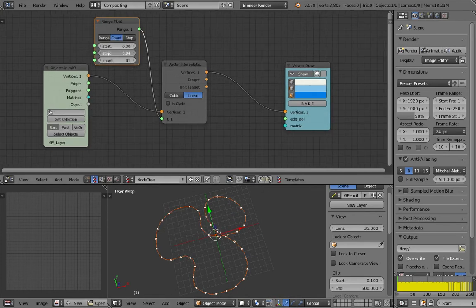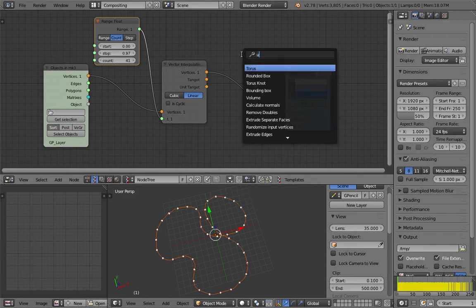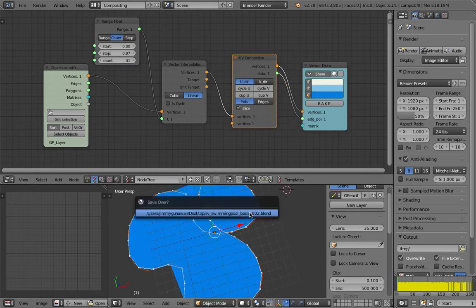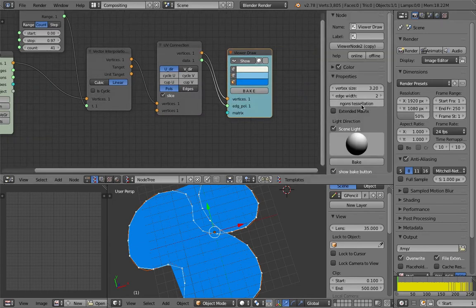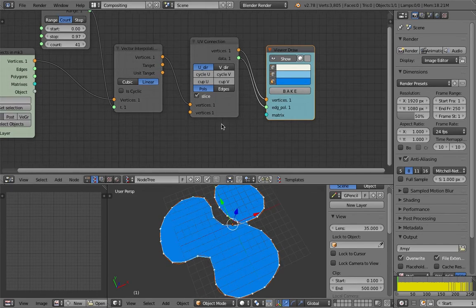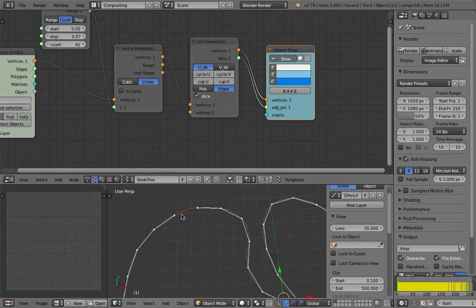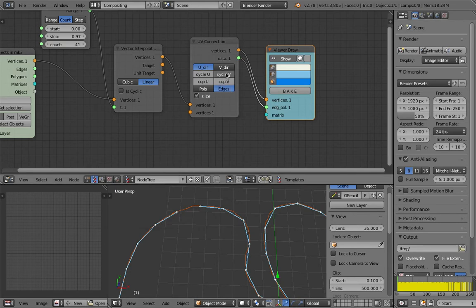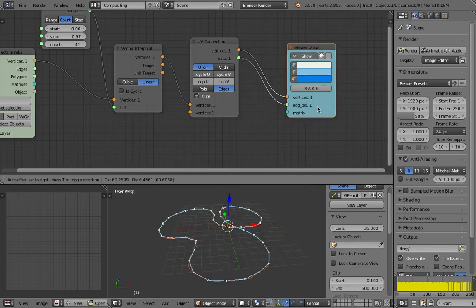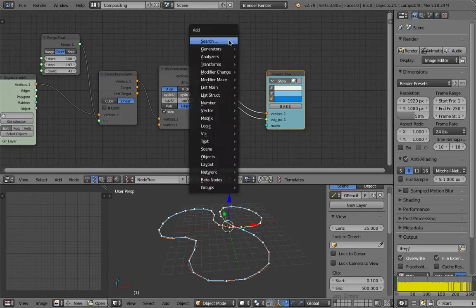Sometimes you actually want to make it not 0 to 1, but just slightly out. And then you connect them together using the UV connection. Like so. Then you make sure here, let me turn on N1 tessellation, and then check these lines and make sure they are connected. See this, the blue lines, we need to make sure it's cyclic. There you go. Now this is a better line to work with.